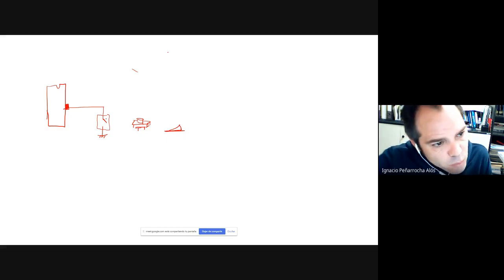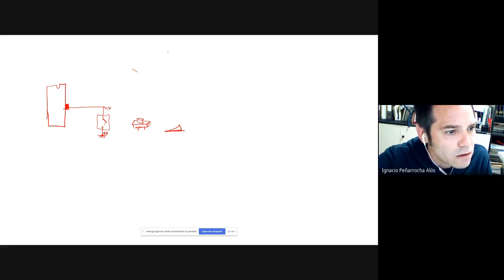When you connect this, you effectively have these 0 volts here. But when you open, you only have high impedance. You don't have anything. You have a little antenna, a wire, nothing else. So in order to be sure that when you open it this is 1, you must connect here a resistor.